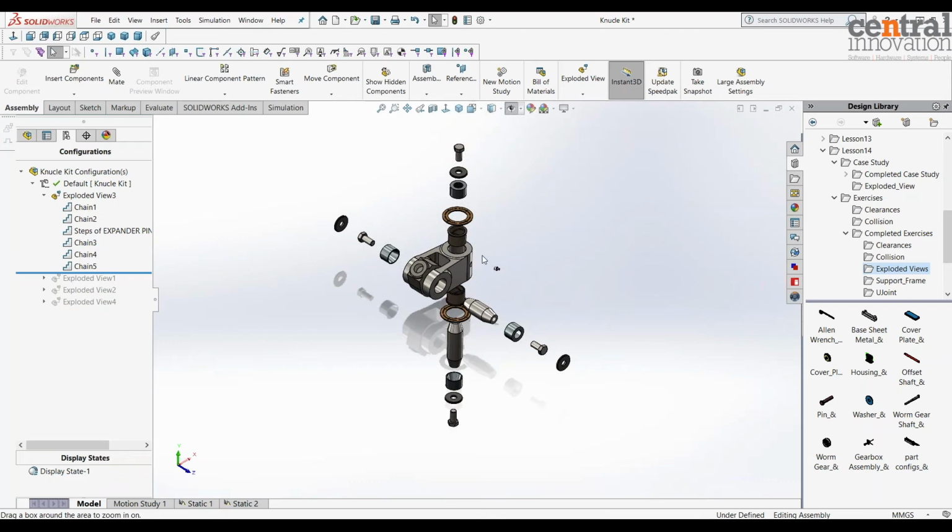The way to check is to simply right click on the sub-assembly that you have inserted, and if you see the option to reuse the existing sub-assembly explode, you can simply use that one, and the exploded view related to the sub-assembly will be added to your steps in the exploded view.